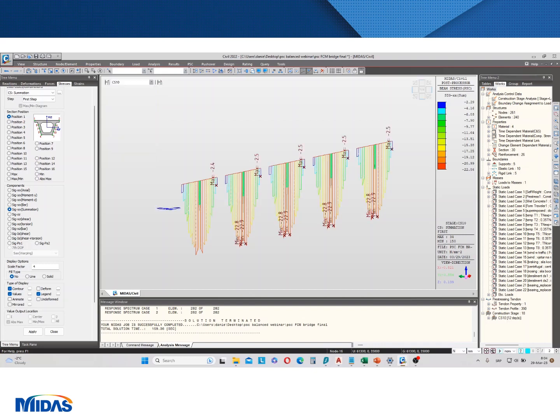So everything is good here. You can see how the structure is coming to closure with no tension in the top fiber. Maybe here at the end a little, but we didn't actually model it 100% correctly. We just left the section from the midspan here, but it's not a big mistake. It can be easily edited.